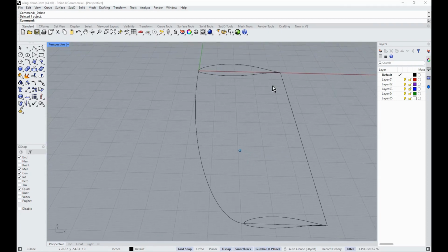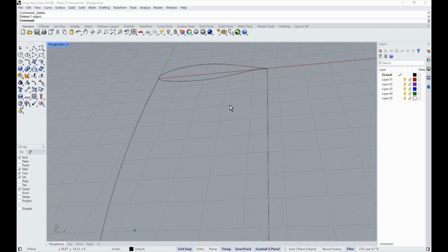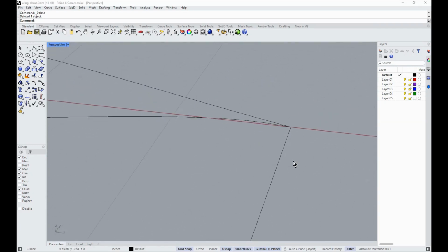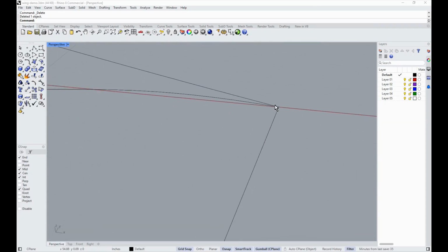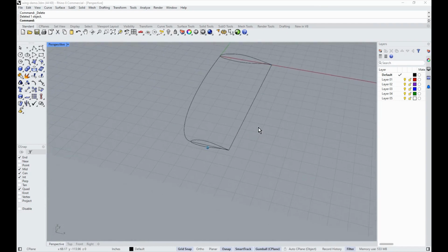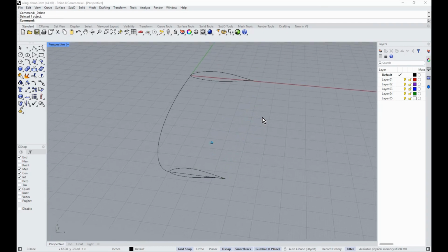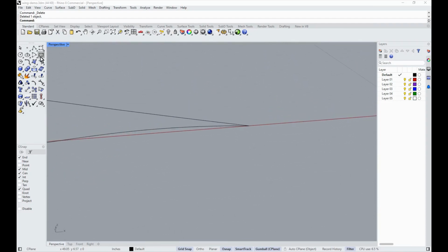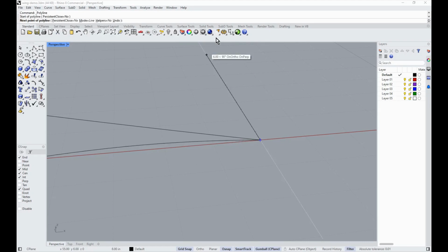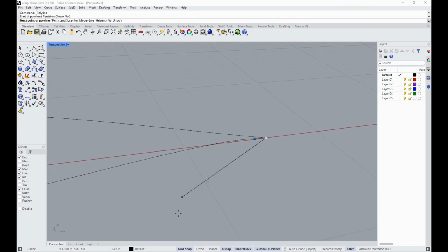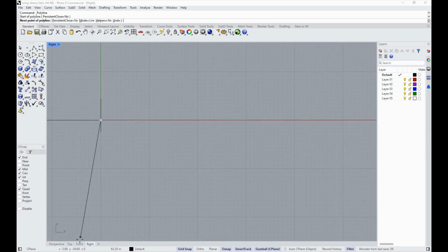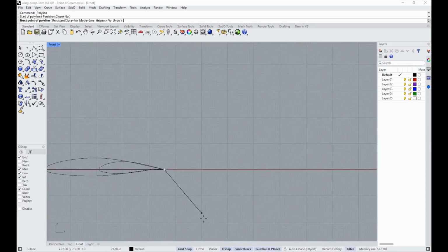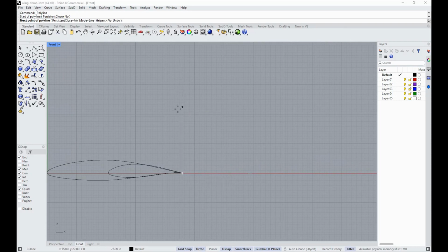So just looking here, what can we go over next? The way these NACA airfoils are designed is to a perfect razor blade trailing edge. That is not realistic in the real world. So we're going to want something like 1/8 inch thick on the end. We'll come into here, and we grab this trailing edge of the root airfoil. We'll go to the front, ortho on, so it's only going to go up, just to make it easy, and we'll go to 0.125. We're going to make like a 1/4 inch thick trailing edge.